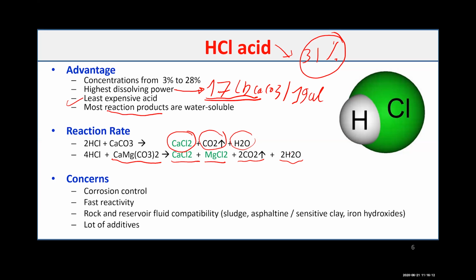And again, one of the things that you like to have is what your starting pH is. Usually when you start with this, the pH of the fluid at initial condition is 0. And the pH after spending is a pH of 4. I wish I had you in class to ask you why you think the final pH will be 4. Because of the CO2.